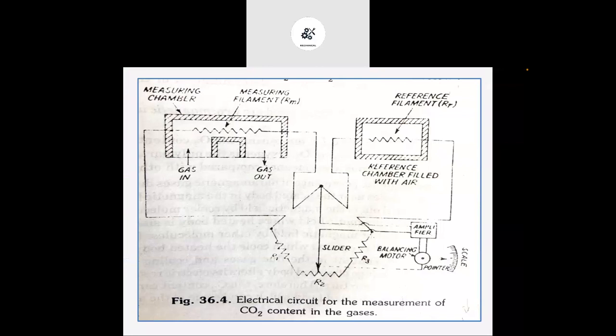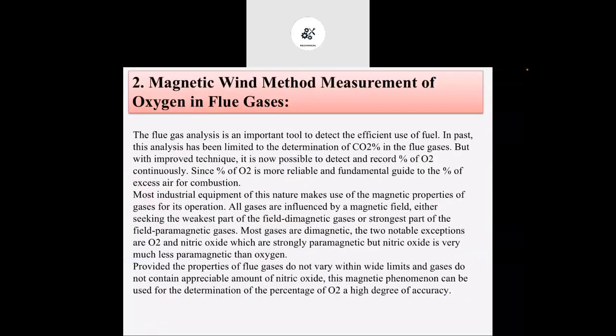As we know, we first have to measure the content of the flue gases. Then we will understand which method we have to apply, or which particular pollutant we have to reduce. Now, this analysis of the flue gases doesn't only give us the idea regarding the solution, but also gives us the idea regarding the combustion process, meaning how efficiently that combustion process has happened.